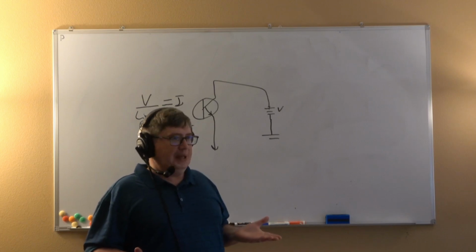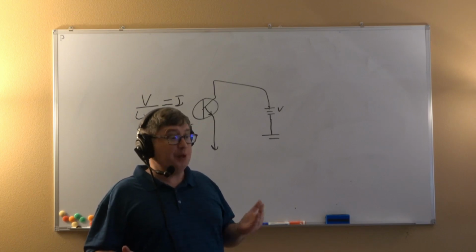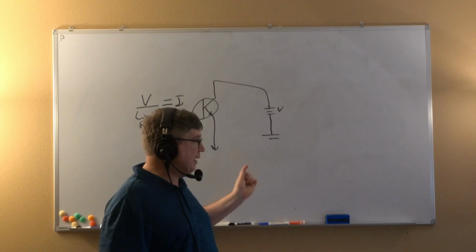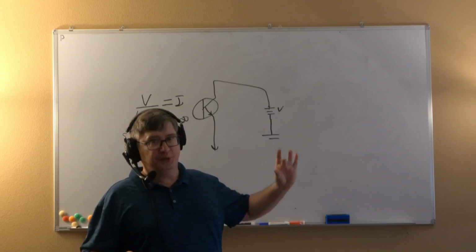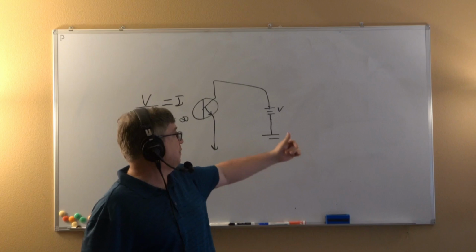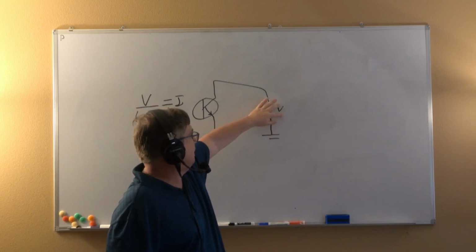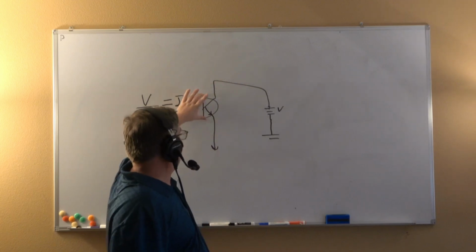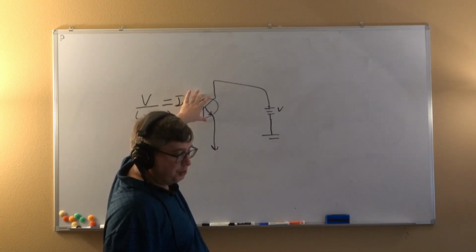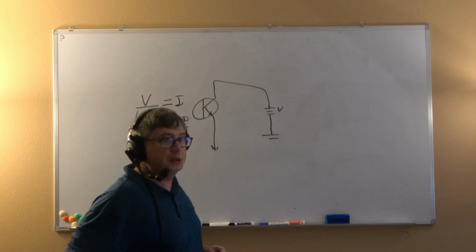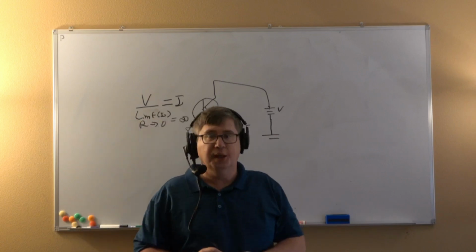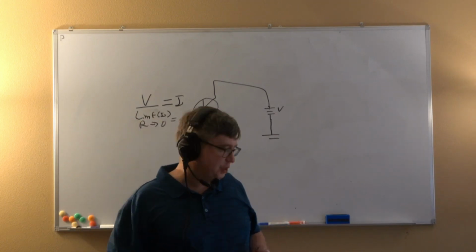It won't really cause it to catch on fire, but you could damage the device, or you could damage the microcontroller, especially if it's coming from an outside source. Like if this V was a power supply coming from an outside source, that could burn up the transistor. Okay, so I hope you enjoy that, and let's go on to the next section.